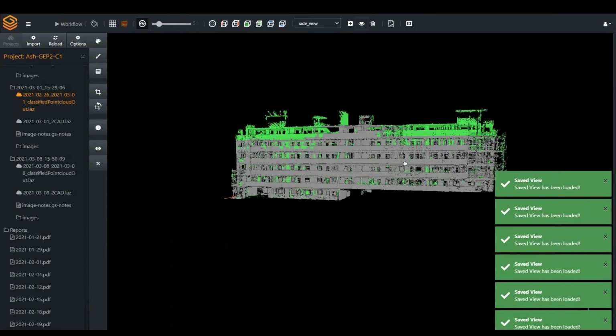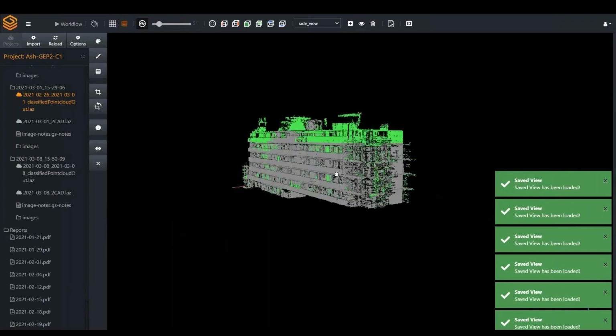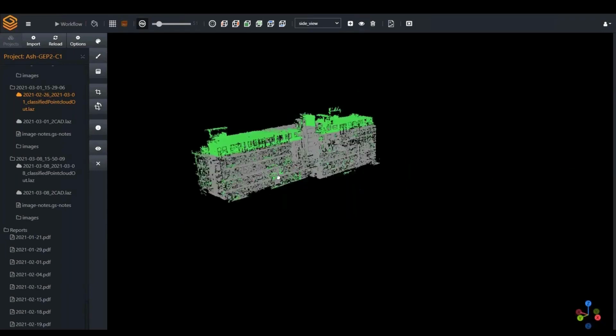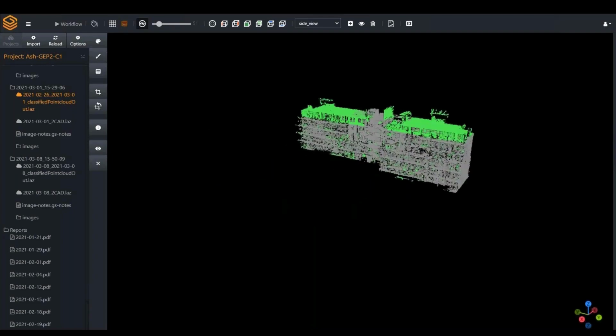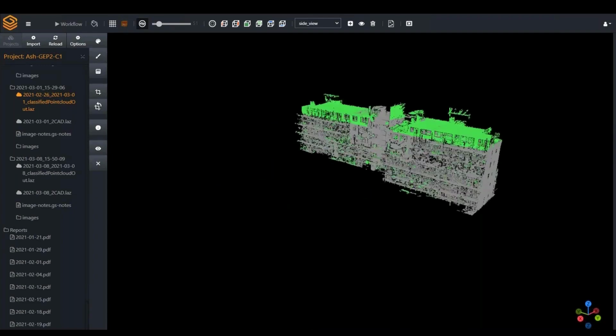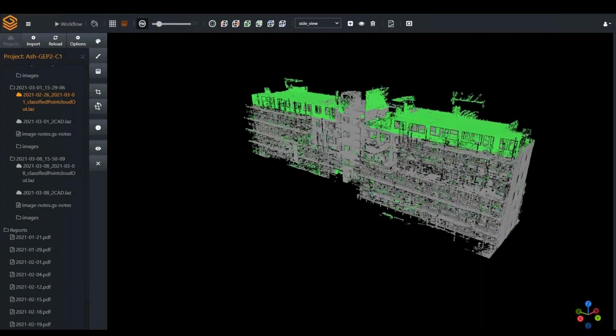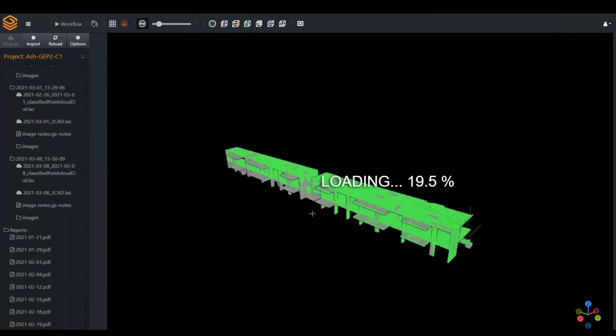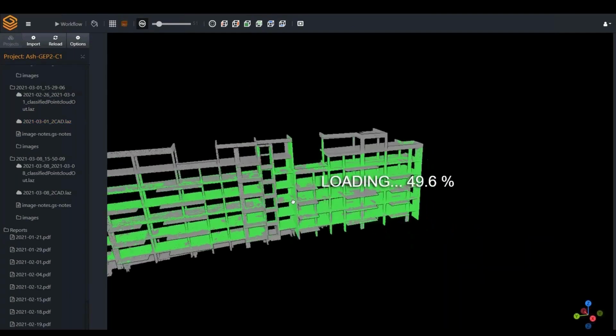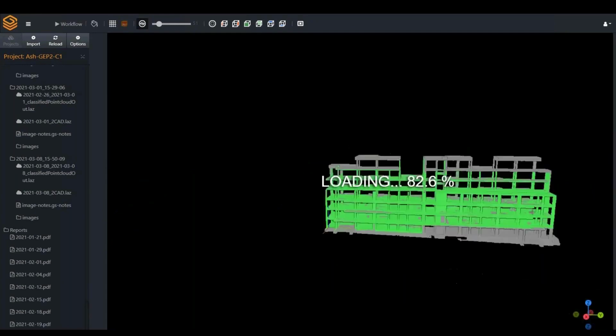There is also, if you are wondering, the way we are able to create this output. We do this with the help of control points that are placed on this site, which are equally distributed. We have around 10 points here that are collected with the ZEP reference plate, where the system is kept static for 10 seconds, and Connect automatically aligns the point clouds together based on those reference points.